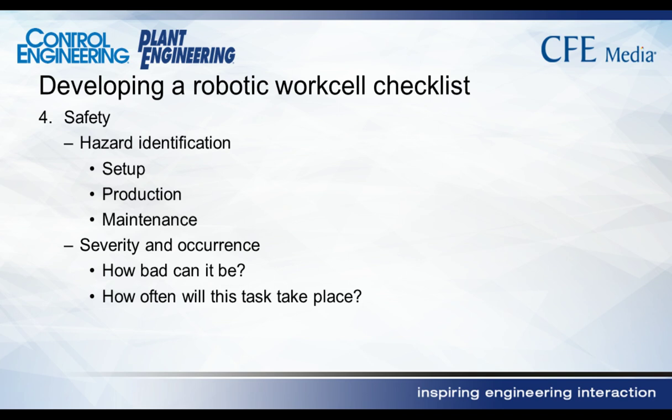So if you hire an integrator to install a work cell, they should be doing a risk assessment, but it should also be signed off on by your team internally at your facility. Some of the things included in identifying the hazards are the process for setup of parts.